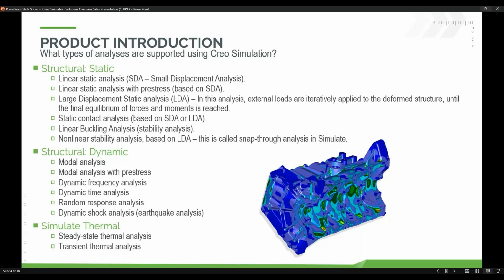We can also do pre-stress analysis with modal. That typically is done primarily, with the example that I can give you, on objects that would have frequencies that would cause the objects to fail. In essence, an earthquake in California. You would want to do a pre-stress modal analysis knowing that, okay, I know what the natural frequency is. What happens to my stiffness as I'm adding components and braces and the like to it?